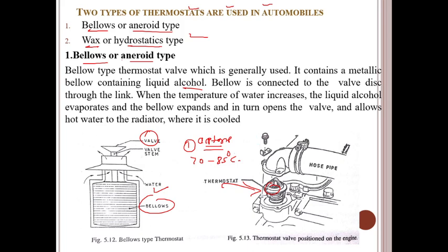When the engine is warming up after starting, it is desired that the cooling system should not operate, so that the engine warms up early. During this period the thermostat valve remains closed because the liquid inside has not changed state and therefore does not exert any pressure on the valves. As the thermostat valve is closed with the coolant pump running, to avoid excessive pressure buildup, a part of the held up coolant is made to circulate back through the bypass to the pump inlet.